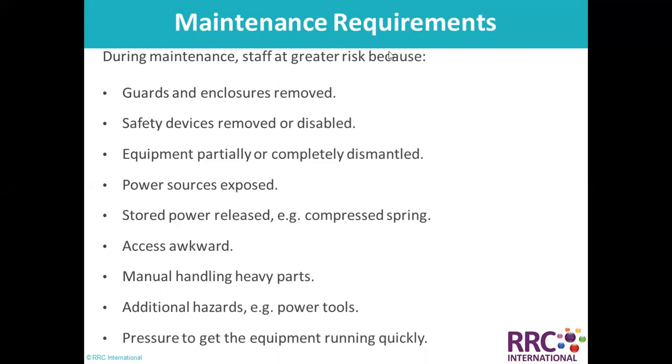So what are the maintenance requirements? Since it's a risk-based activity, during maintenance staff are at greater risk because guards and enclosures are removed, safety devices removed or disabled, equipment partially or completely dismantled, power sources exposed, and even stored power released, like a compressed spring. Access could be awkward, and there is manual handling of heavy parts. Additional hazards could be power tools and pressure to get the equipment running quickly.